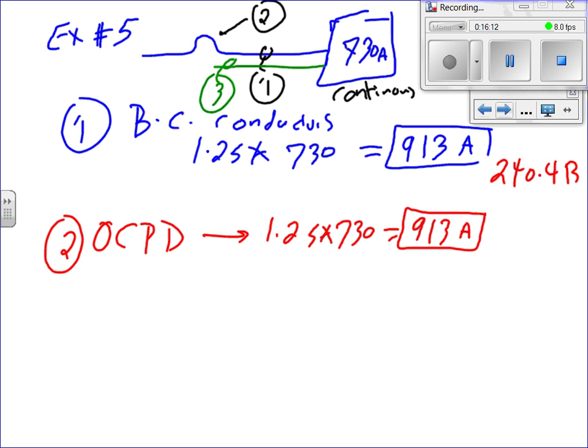If you look at 240.4 B and C, it says that as you size your overcurrent protection device for a conductor, continuous or non-continuous, you can go up to the next standard size until you hit the ceiling. What's the ceiling? 800. When you hit the ceiling of 800, then you have two options: either you lower the overcurrent protection device, or you match the conductor to the overcurrent protection device.